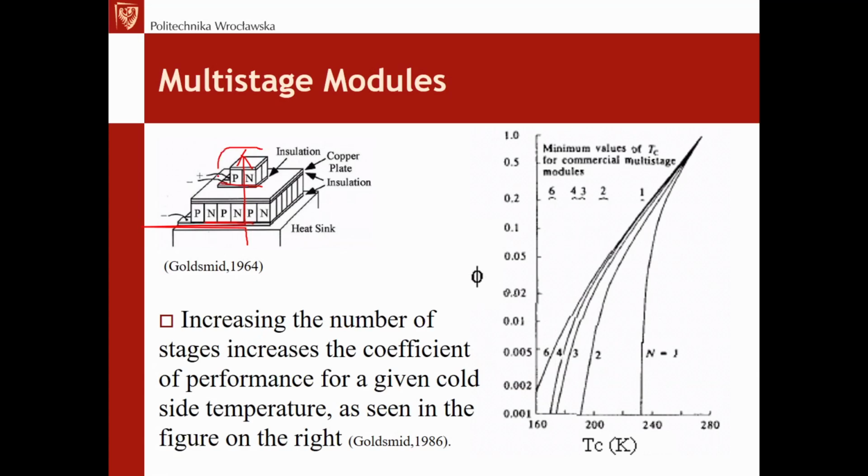So of course this element is not pumping out the heat itself from the bottom one. We still need a very good heatsink here to be connected. So this additional stack of Peltier elements is not solving the problems of proper heat sinking at the hot side.